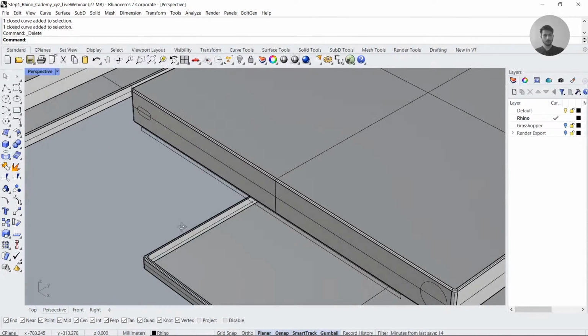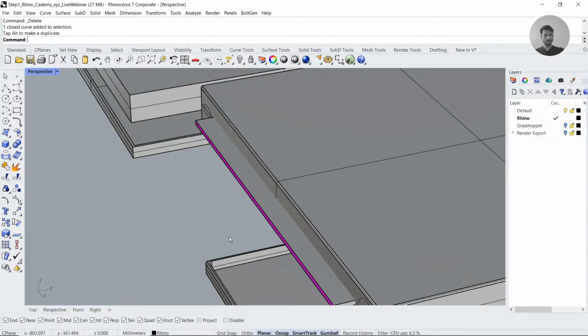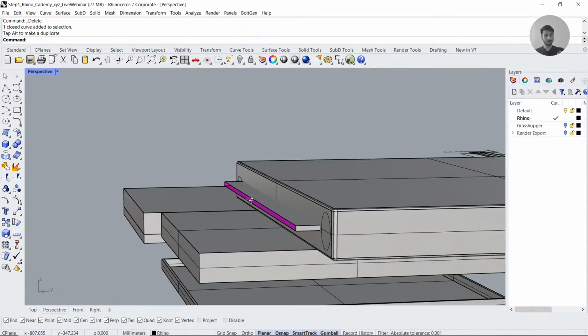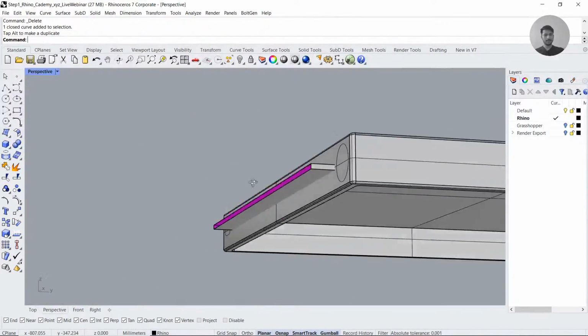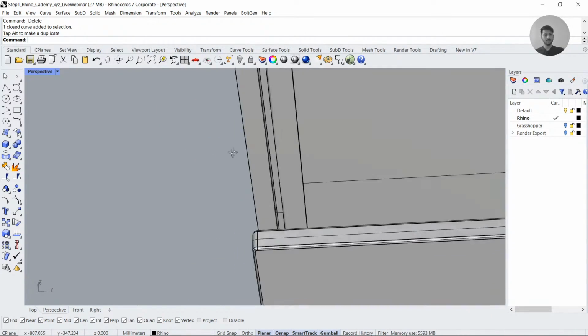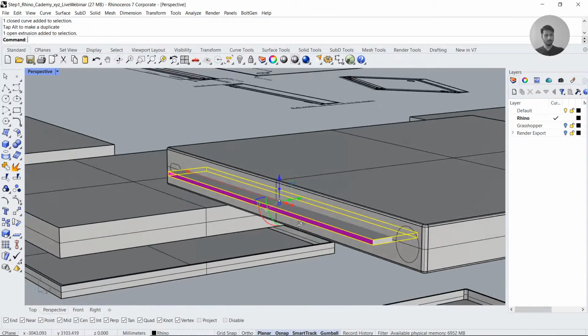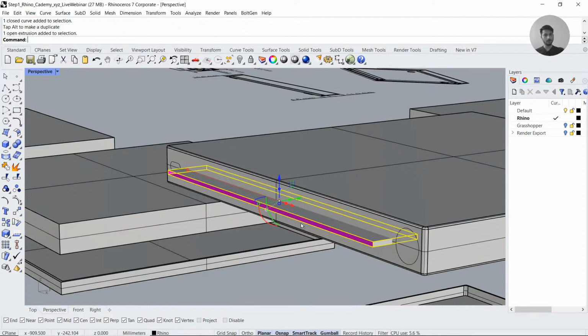Okay, great. So I was talking about extruding this curve. So you can extrude the curve by dragging this circular button, and it will create an extrusion of that profile of the curve. As long as you are completely covering the geometry, it doesn't matter if this surface, if that geometry is an open poly surface or a closed poly surface.